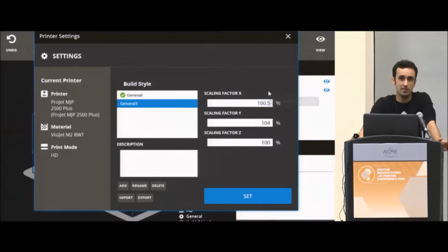Sometimes turning off every other layer might help with shrinkage, or turning on all the layers in printing, because sometimes the infills don't scan on every layer, sometimes they scan every other layer. Subtle little changes like that can have a big impact on the overall shrinkage of parts. But a lot of that is sadly trial and error currently. I don't think we have a simulation software that simulates the shrinkage of parts accurately enough. Not that I know of. It might exist, I just don't know of it.